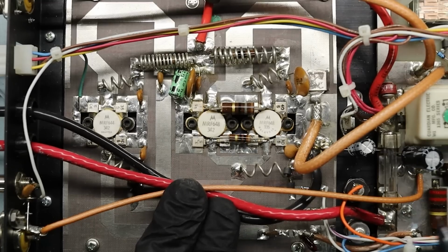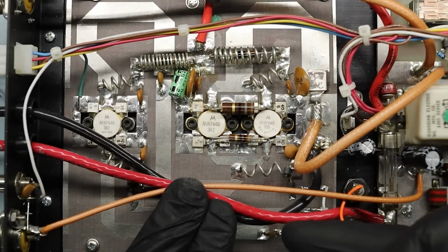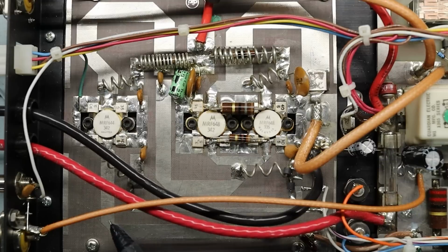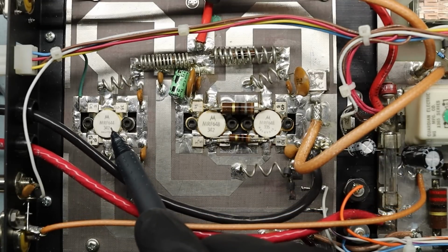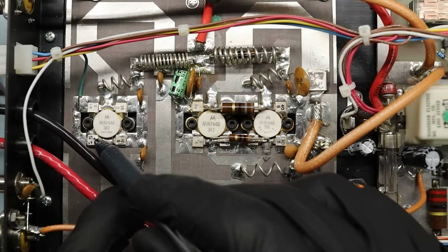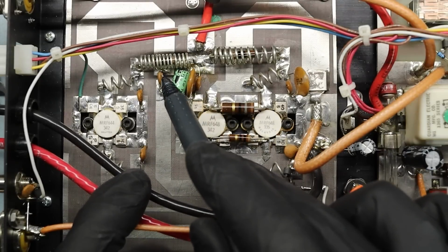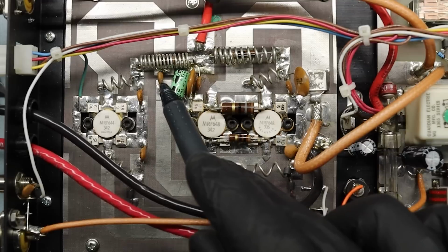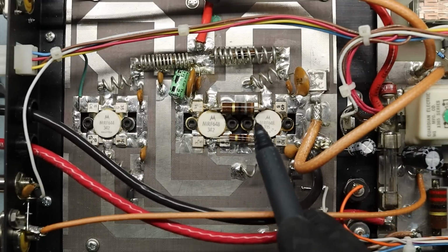So this is the part that I wanted to look at. So you can't see the entire thing, but I just wanted to focus on a couple things here. Our RF signal comes in over here, okay, along this big fat trace and feeds into the base of this MRF 644. That is an RF transistor, power transistor. We've got all these little capacitors over here that help decouple the signal, and then it goes all the way over here through this feed-through capacitor, and this is what separates the Class A stage from this final stage, okay?